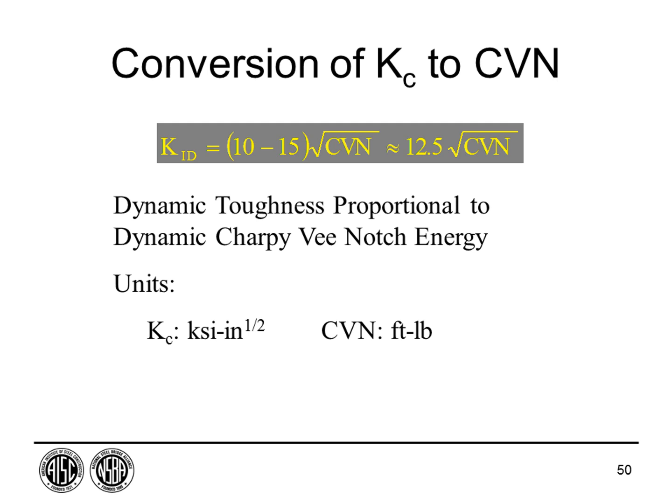Now we use the Charpy specimen to check out our steels because it's a reasonably inexpensive test. If we go to a true fracture mechanics specimen, that means we have to pre-crack it, and it's very expensive to do. So we use this to screen our material.